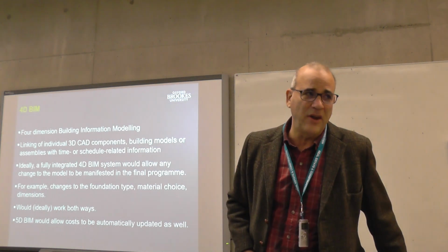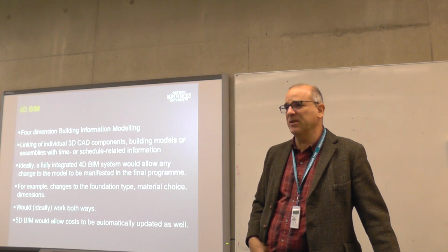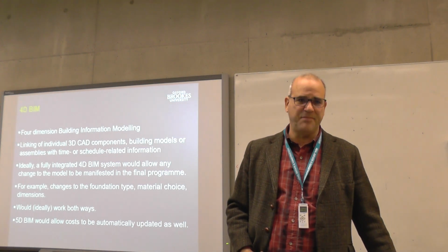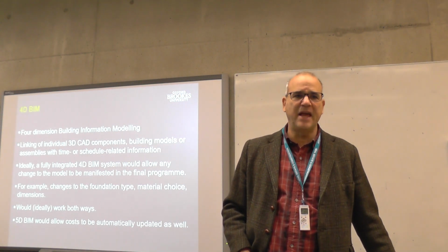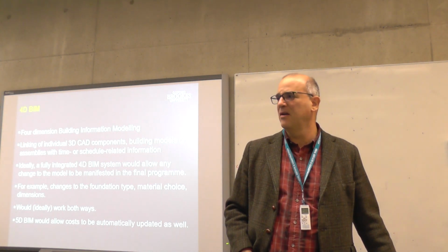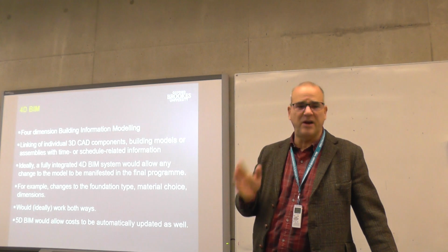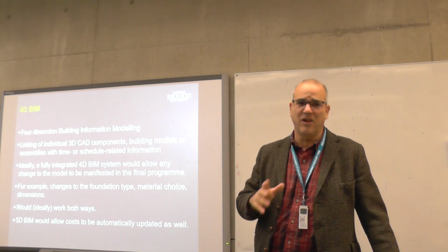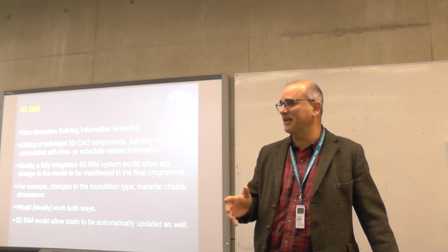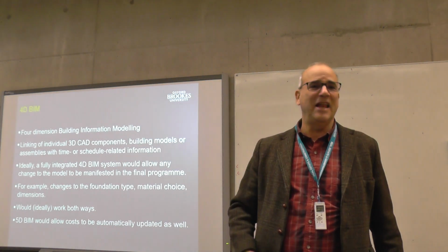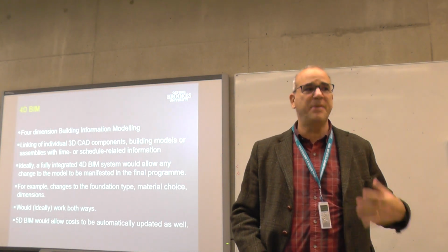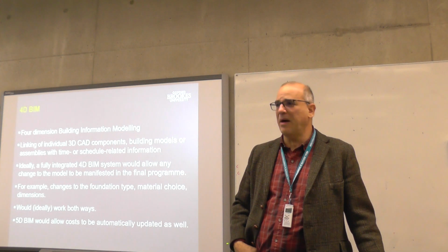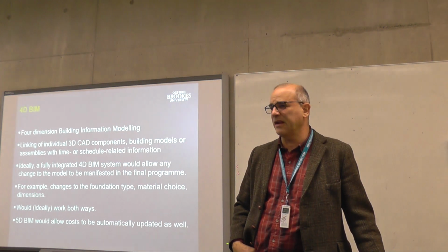One issue going on now in the industry is that buildings over 18 meters are not allowed to be made out of wood anymore. And that's because of the latest regulation change due to the Grenfell fire. So all of a sudden, on the drawing boards of architects and designers all over the country are wooden buildings of 23 meters plus, and they're going to have to redesign them in concrete or steel. So we've had an abrupt step change in the regulations that is going to cause a redesign.